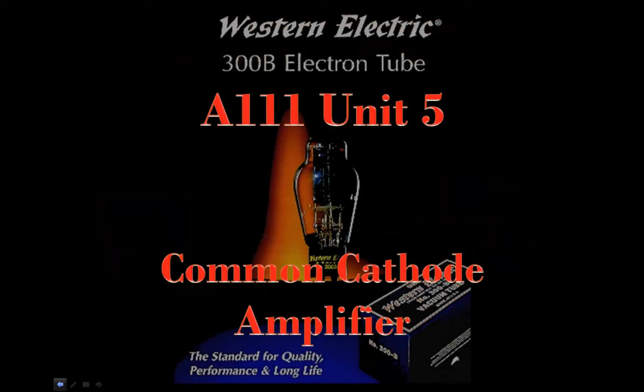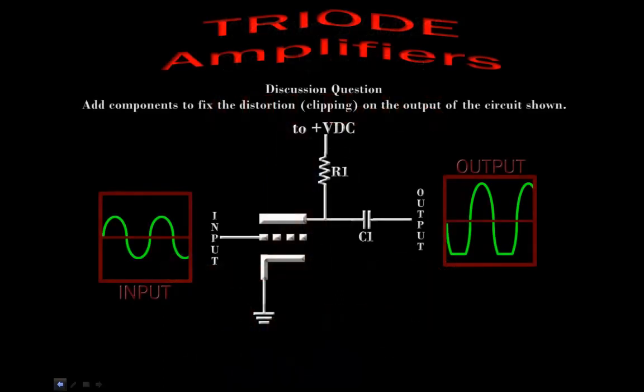We're going to look at a common cathode amplifier in a little bit more detail and a little bit more of a real-world example of it. So here we have the common cathode circuit as we've looked at it. We have a resistor going from the anode to the positive voltage. That's there to convert a changing current through the tube into a changing voltage for our next section.